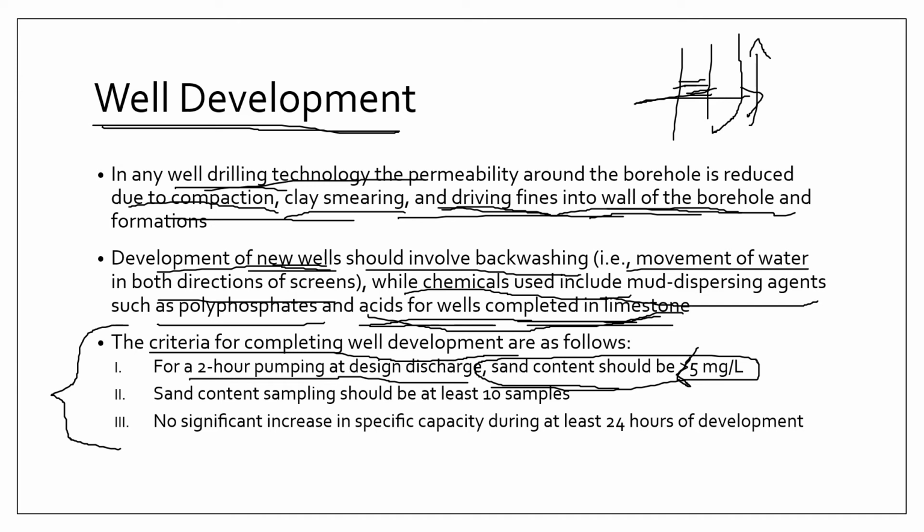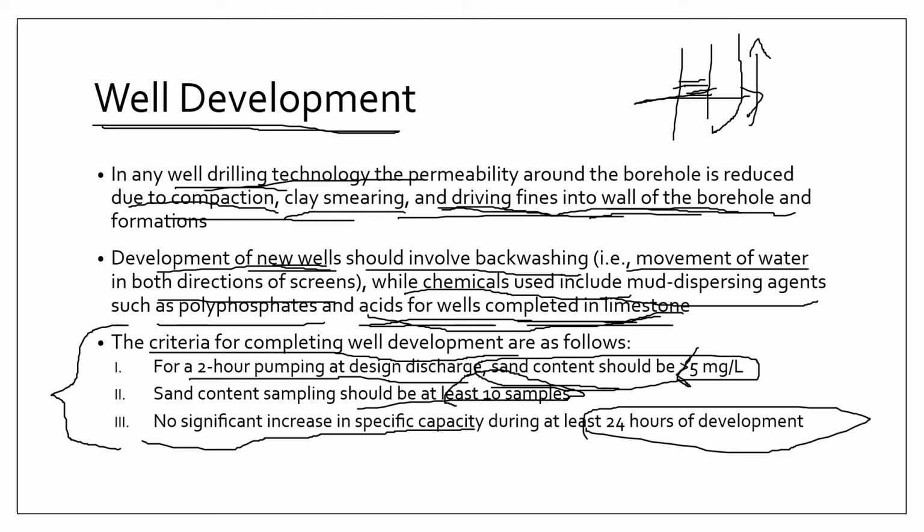And this should be measured by at least 10 samples. And then there should also be no significant increase in specific capacity or specific discharge for at least 24 hours. Or it means that the pumping rate or the discharge should be more or less steady for 24 hours.